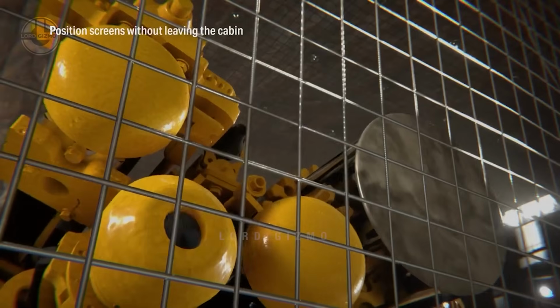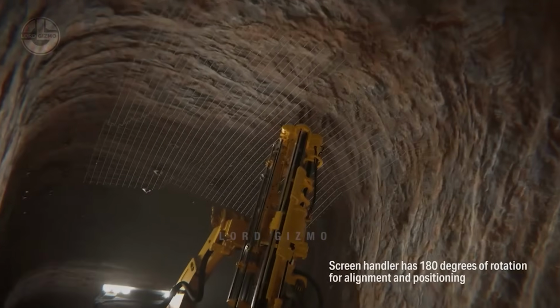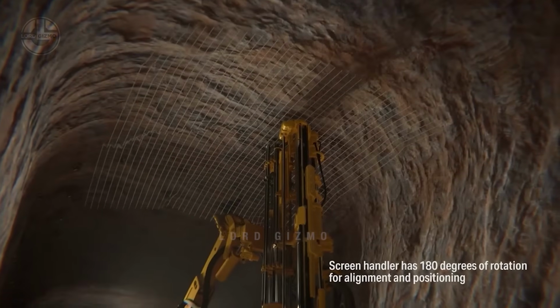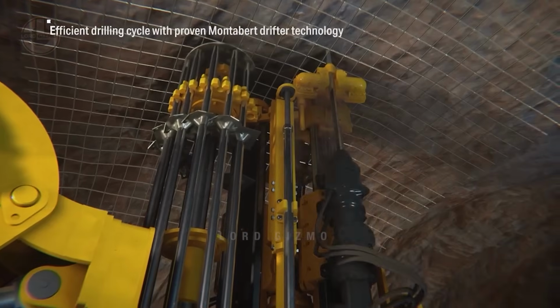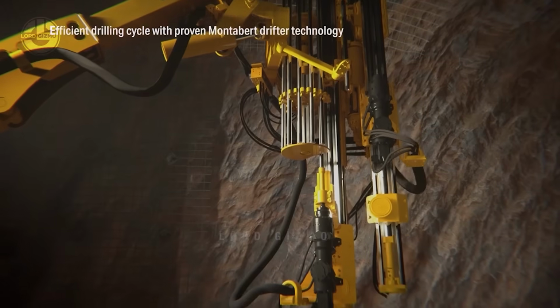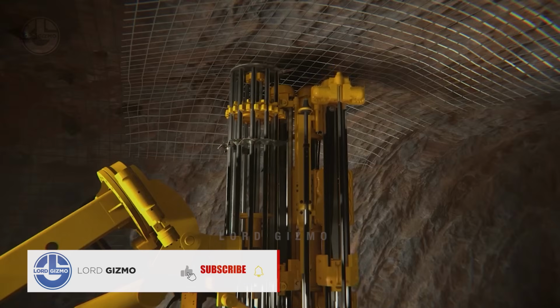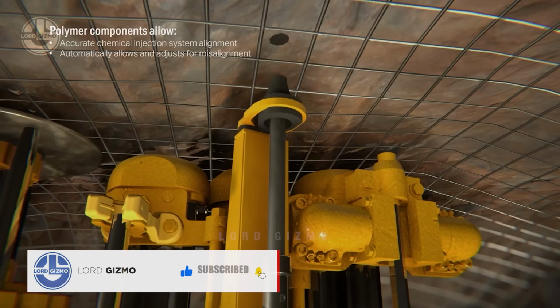To mitigate this risk, one solution is bolting, involving the insertion of metal rods into the tunnel walls and sealing to reinforce and hold the rock or soil in place. To do this, they insert a steel rod into a hole drilled into the roof or walls of a rock formation. This can be done in 3 ways: mechanical, grouted, and friction.